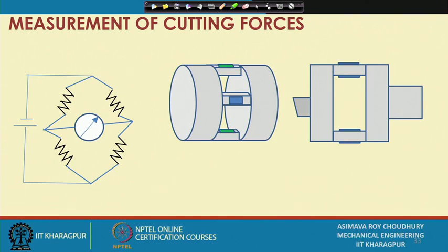So, this proportionality allows us to measure resistance and accordingly predict the strain, and that means, within elastic limit, the stress, and from that the force. Naturally, with some known force values we have to calibrate the machine, so that we understand which particular change in resistance stands for what particular force. Now, how do we measure this change in resistance and utilize it for our values?